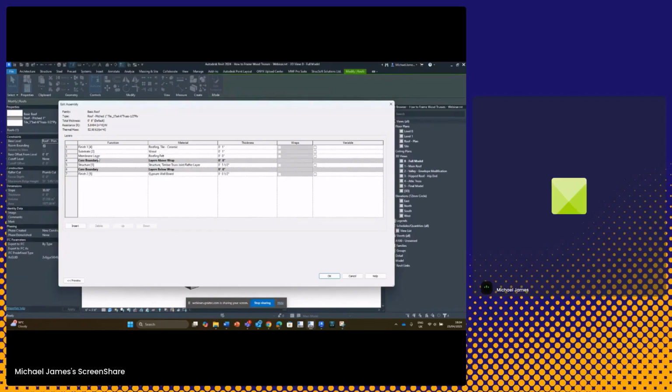Our framing members are then placed after our membrane layer, which has 0 thickness. So what I need to consider right now is the 2 inch layer that we need to leave free for the substrate for our wood battens and our roof tiles in this case. So I want to place these structural framing members 2 inches from the top. Okay, so we'll bear that in mind when I start framing and it will make sense.